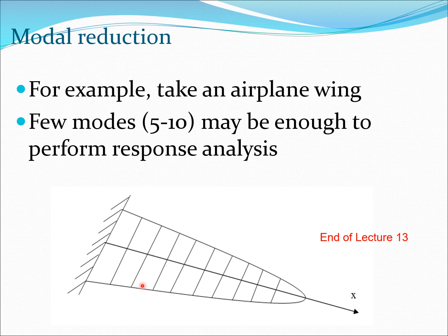Of course, remember that we are assuming to a large extent, or to a complete extent, that these are linear systems, so things are all working out very well. So for linear systems, we can certainly say this is a good way to go about it. Modal truncation is the way to reduce the size of your problem.